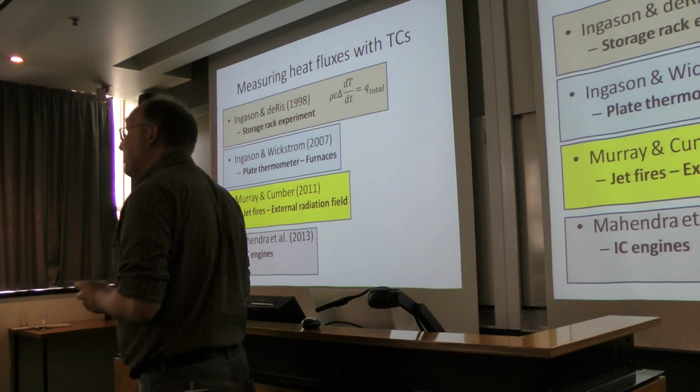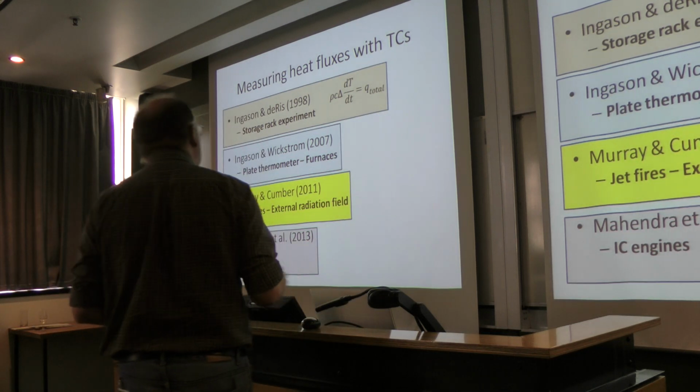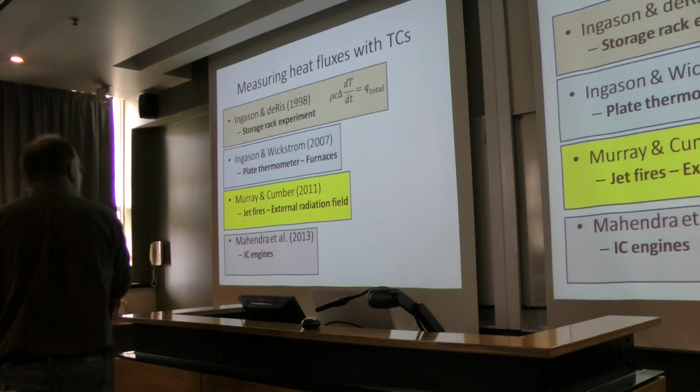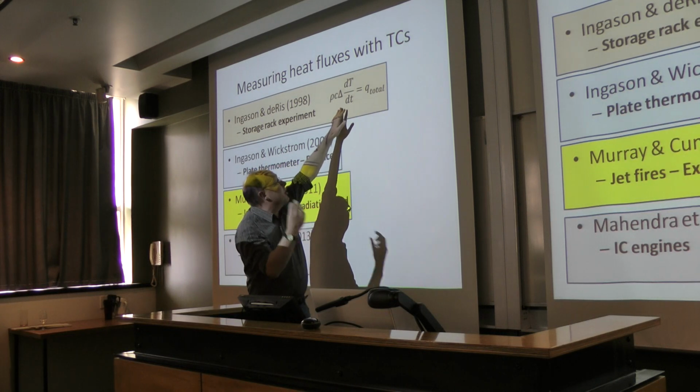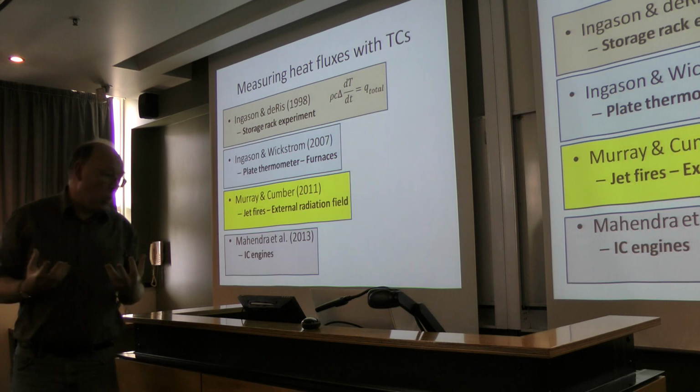So they wouldn't have been able to instrument it out in that way with normal heat flux gauges. Their model, or the heat flux model they use, as you've got it up there, has a term for the thickness of the little piece of metal that they attach their thermocouple to. And what they were measuring was the total heat flux.